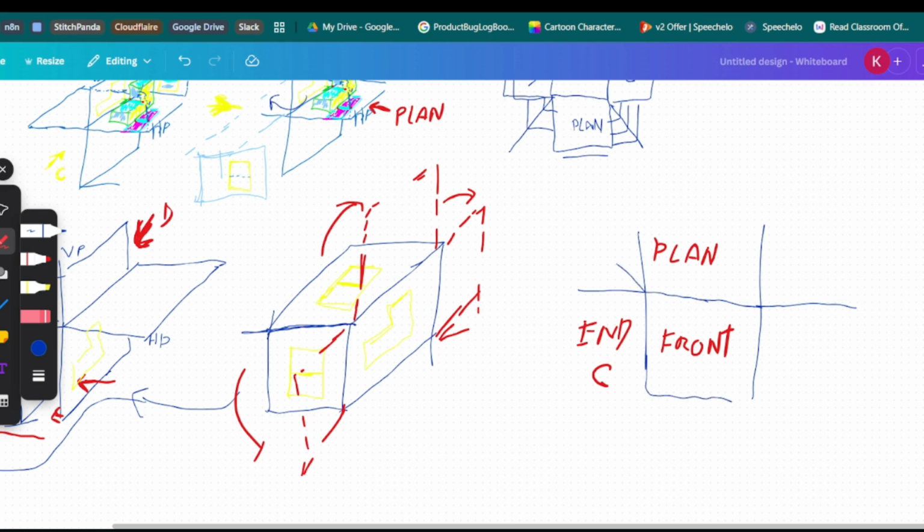Of course, I'm going to put my 45-degree angle here because it will be inverse, since we want to transfer some of the dimensions onto the plan from the end elevation. You know we always have to do that, right? The end elevation for the view from D, which is from the back of it, will now come here. So D will come from this.